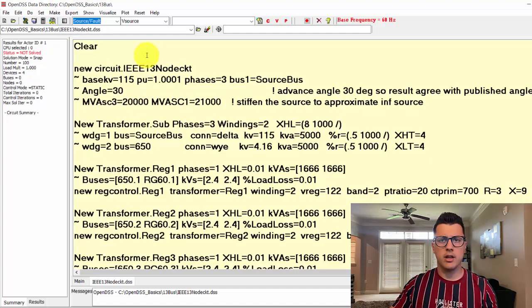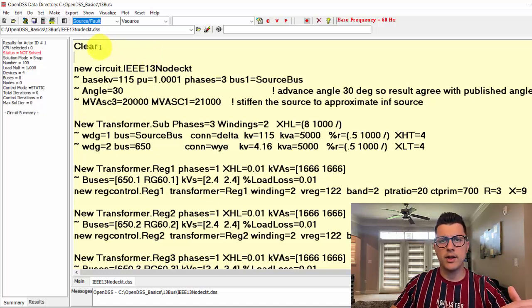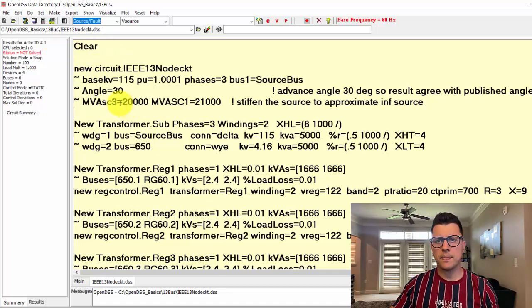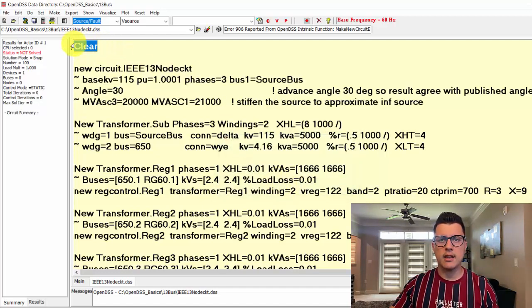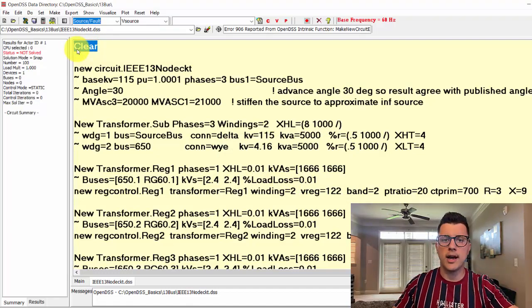But be careful. You see that when I'm running the same code, I always consider the clean before. For instance, let's say I clean everything, and then I run that, and when I run that again, OpenDSS will tell me, well, this is something I already have in the model. So always try to clean OpenDSS memory to allow you to run again all those lines, or in other words, the same element.